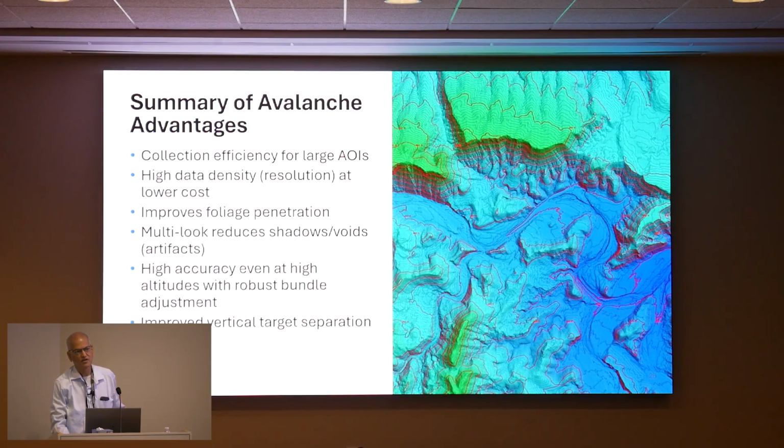So now there is a thought process going on whether you can have a combined program. That means both the utility agency and the government agencies come together in a sort of consortium. You collect the data at higher density, 30 or 40 points, and that data set can be utilized by the utilities. Then out of the 40 points, you downsample the data to 8 points and give it to the state and local agencies, and they can use the data for their application.